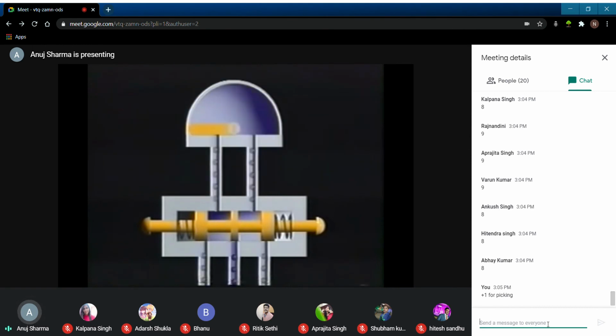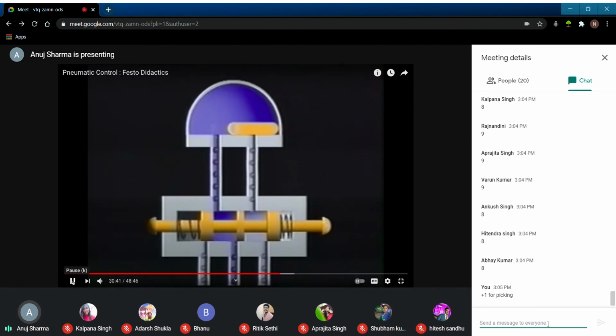The 5-3 valve can be used to control the position of a rotary vane double-acting cylinder. The valve port connections are the same as the 5-2 valve. Both upper ports are connected to the cylinder. The lower ports are exhaust, air, and exhaust. In the valve's initial position, all ports are blocked. This holds the vane at its current location. Pressing the left push button sends air into the left side of the cylinder and exhausts the right side.